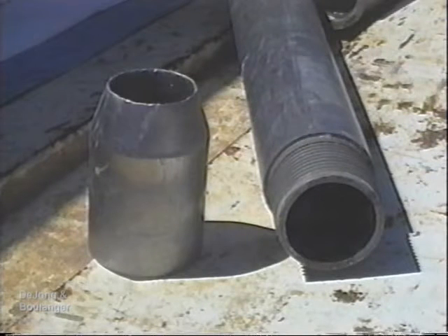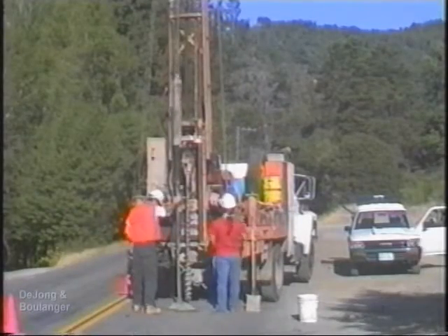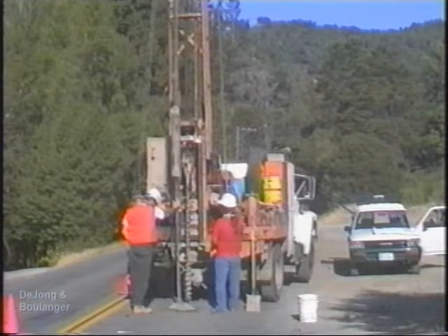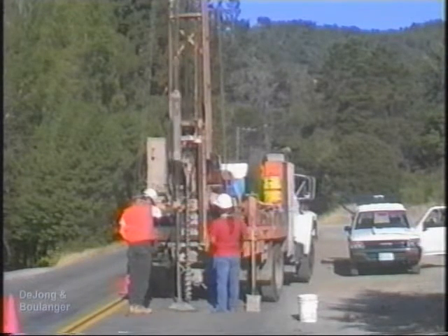The split spoon sampler must have an outer diameter of 2 inches and a constant inside diameter of 1 3/8 inches. Liners may be used only in modified split spoons that maintain a constant 1 3/8 inch diameter inside the liners. If a modified split spoon with room for liners is used without them, the N values are generally 10 to 20% smaller. The amount of energy delivered to the sampler per hammer blow should be 2,520 inch-pounds, which is 60% of the theoretical maximum.